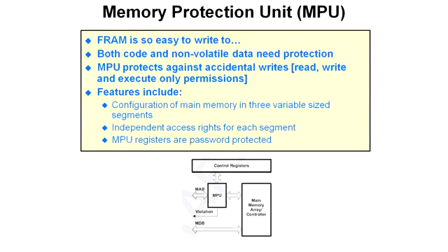The MPU registers, the memory protection unit registers, are password protected, so you don't have to worry about them getting changed. Any violation of those constraints, the access rights, would generate a fault and put you into your fault handler.